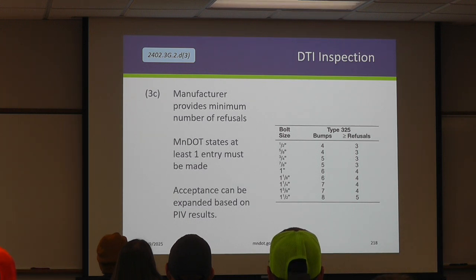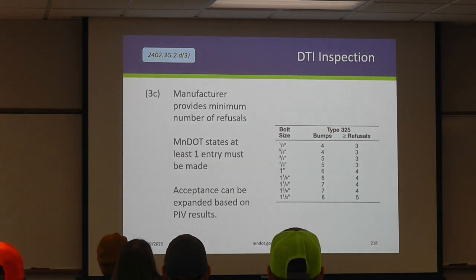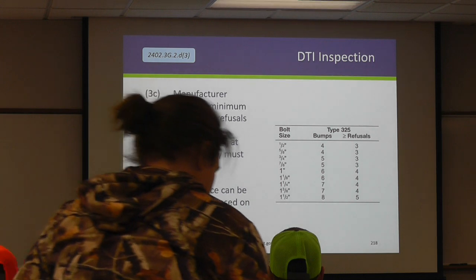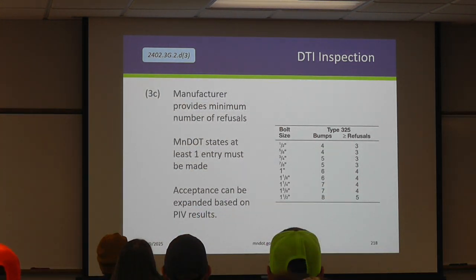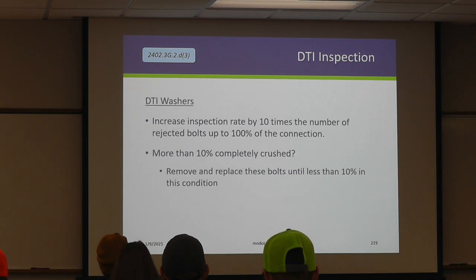I will tell you that since we put in the spec book the multiple of 2 passes for snugging, that problem has substantially gone away. It comes up from time to time, but it used to be almost every steel bridge we'd get calls on this. And last year, we got a call on one, and it was partially because they were using the wrong size bolts. It's really important, that snug tightening procedure. I can't emphasize that enough.